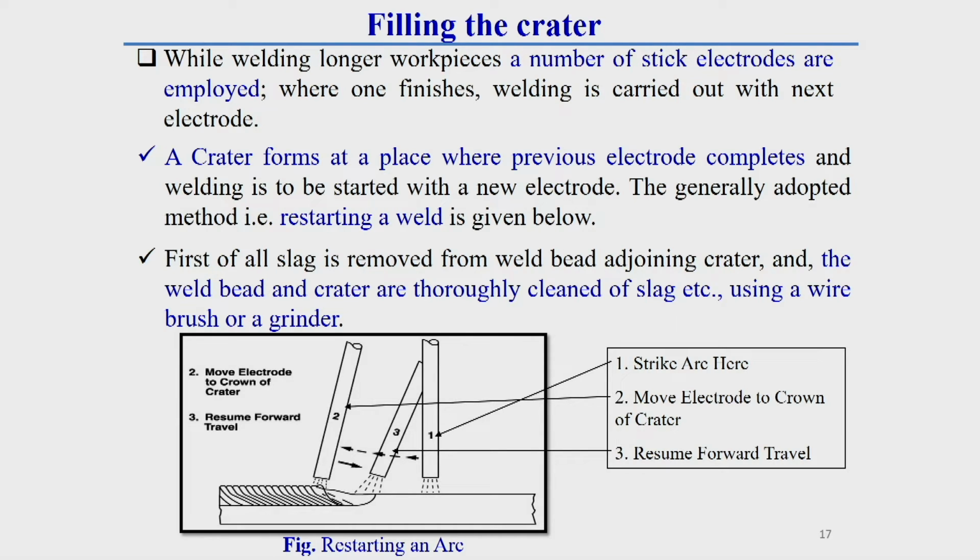After that you do the restarting, because if it is not cleaned properly, there is a chance of slag inclusion inside the weld material, which is also a defect. So we should clean it properly. Then this sequence of the restarting procedure is required.